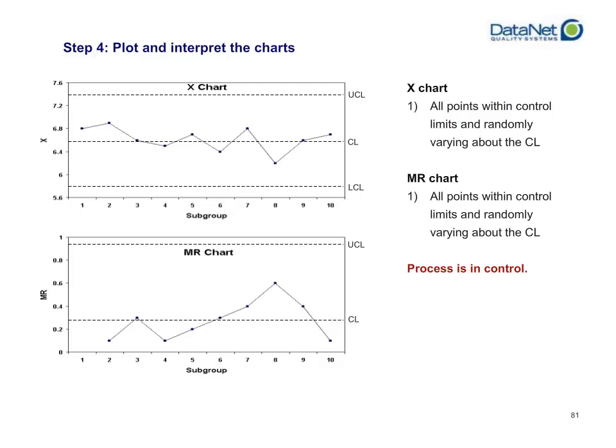From what we can tell from the X chart and the MR chart, there are no points that are falling out of control. Therefore, the process itself is in control. Now, that's not to say that there might not be something you want to investigate. If you had your own set of control rules that you wanted to follow or something that you wanted to recognize, having this plotted out in a control chart, you can still begin to see patterns, but in the strictest sense from how you calculate control limits, all points are within control and are randomly varying about the center line, as we demonstrated earlier on when we showed different types of control scenarios and control violations.